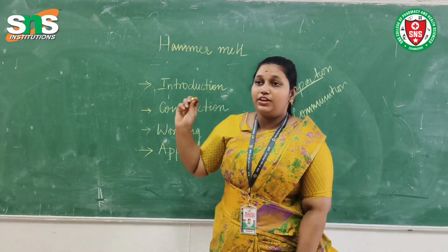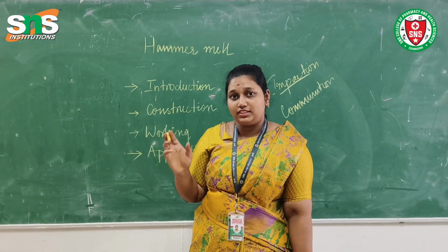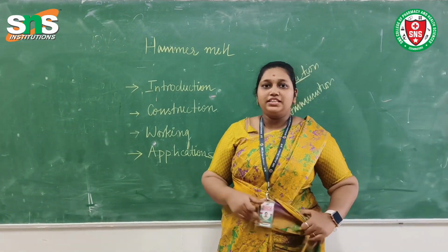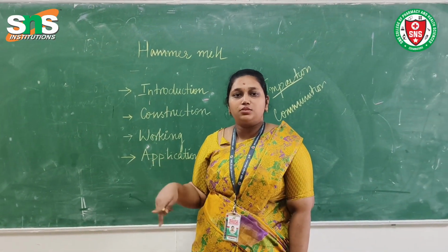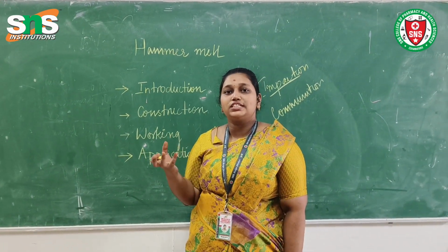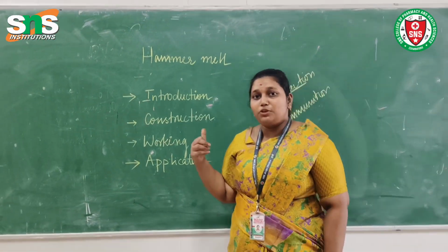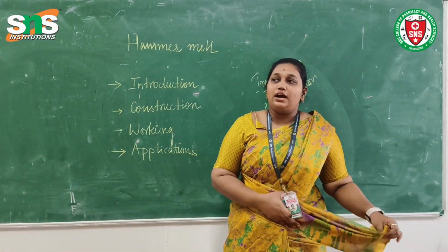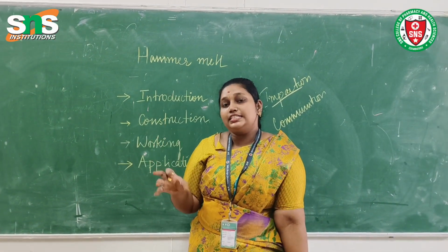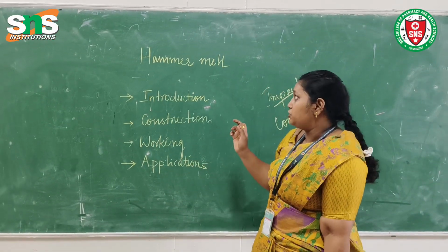Impaction is nothing but when we keep a product which has to be size reduced in a stationary place and apply an external object which is in a circular or continuous motion to hit this object and further reduce the size of the stationary object; this is called impaction. Comminution is when we apply a mechanical or external force on a stationary product, so its size gets reduced into smaller sizes; this is known as comminution.